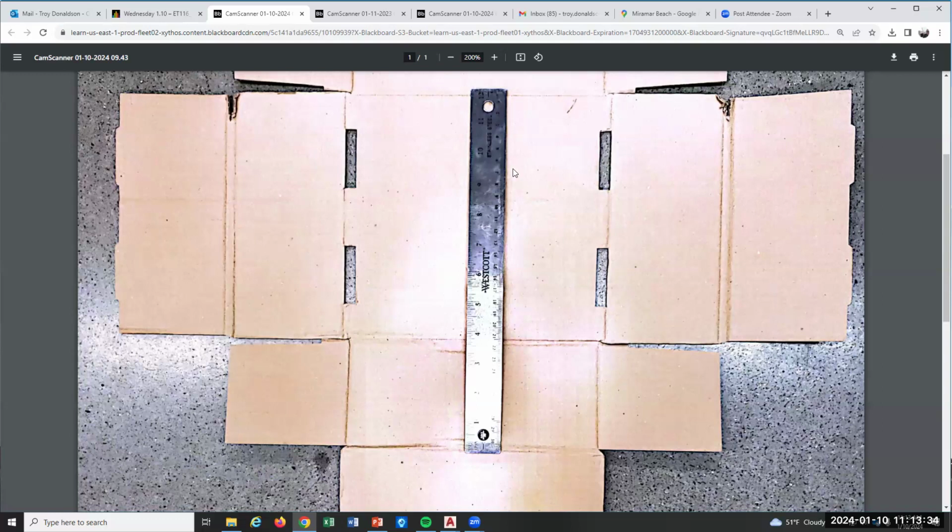So what I want you to do is you're going to bring in the PDF. You're going to scale the PDF appropriately, and then you can just trace it in AutoCAD. It's super slick. It'll be plus or minus the accuracy of the picture, which who knows how accurate the picture is. You can see some of the pieces are kind of leaning at an angle.